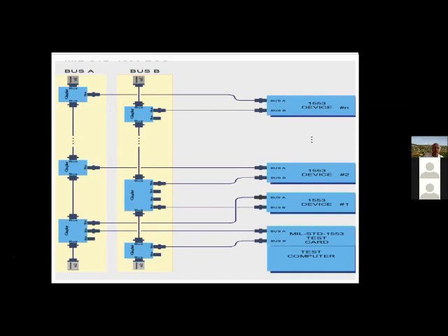But the important things to see here are that bus A is going to 1 active bus. Bus B is going to a second one. Both buses at the ends have these terminators, top and bottom. You're allowed to have empty stubs. Sometimes people put smaller terminators, like 3 ohms as opposed to 70, which is the terminator at the top. We found that to be less critical. Right, so that's what the topography of a bus actually looks like on an actual aircraft.